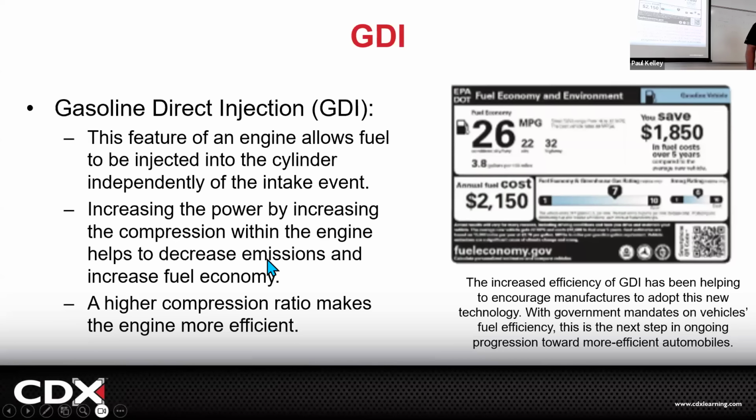But when we're running a higher compression, we've got to be really careful with our air-fuel ratio. And we've got to have higher processing speed. We've got to keep an eye on this thing. Generally a higher compression would mean higher octane, but if we do the GDI right and clean at the right ratio, we can still have you run 87. So that's what we're doing here.